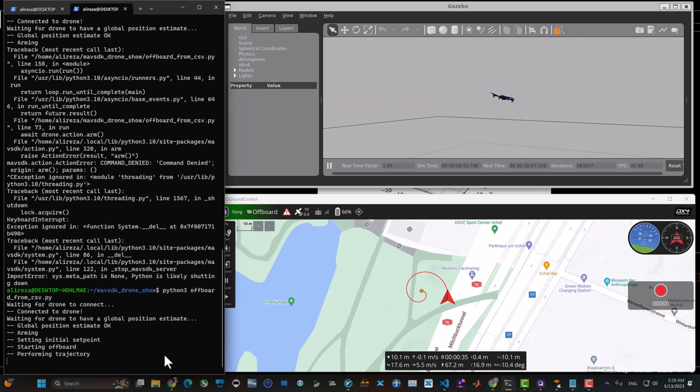For example, you have a Raspberry Pi on the drone. At the exact same time, you're going to start the mission on each drone, and the drone will continue following the trajectory. But it's not that simple in the real world. You should always have extra consideration and fail-safe consideration to check if the trajectory is being followed correctly. Otherwise, your drones might end up colliding with each other.